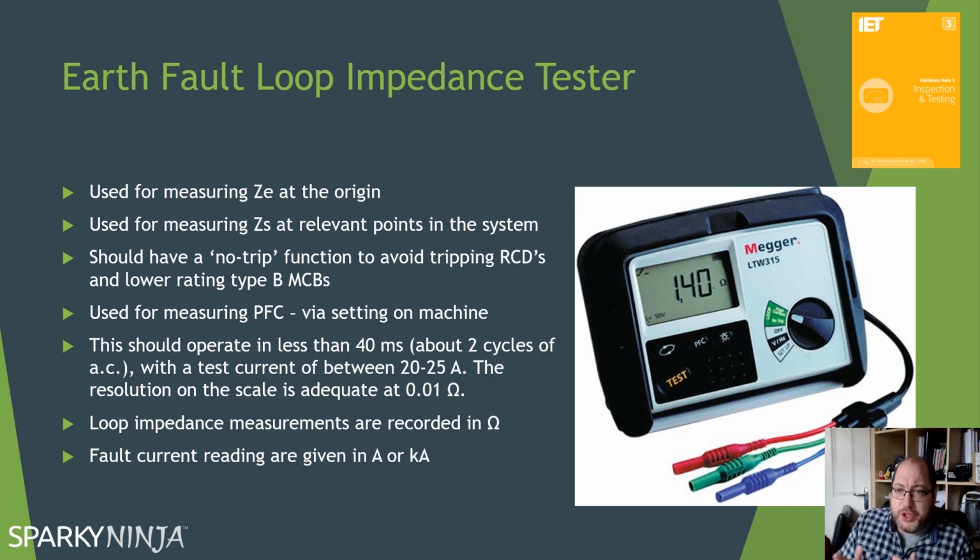I also would use a value in my area where I do work as well with arc flash. So I would do a value of live to neutral loop, so I can actually get an understanding of the impedance of that path as well for arc flash calculations. But yeah, do be aware of what the testers can do.